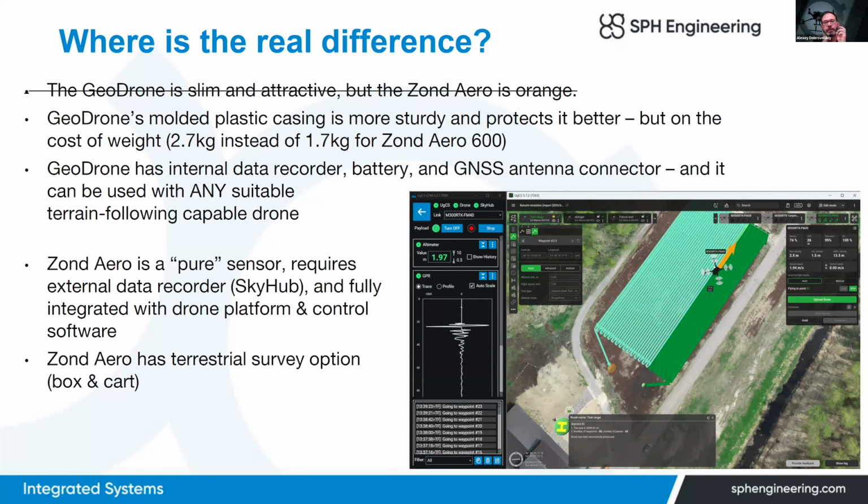Actually, MALÅ GeoDrone has a Wi-Fi access point, and from 10-20 meters, maybe 30 meters maximum, you can connect to that Wi-Fi hotspot and see data from the GPR in real time. But in the majority of surveys, the distance will be much larger, and you will be able to check the data only when the drone has landed and you download the data.